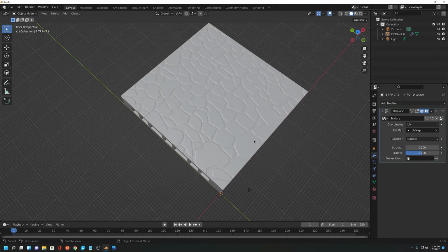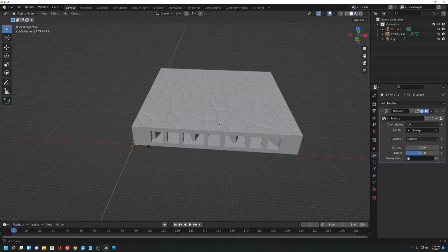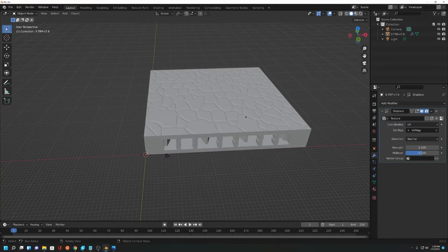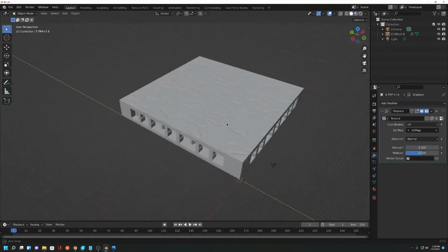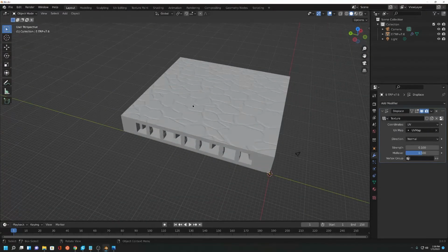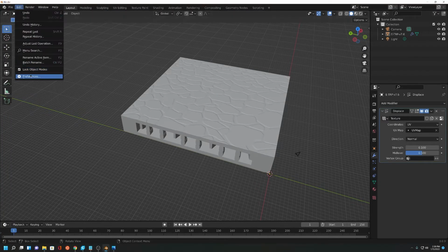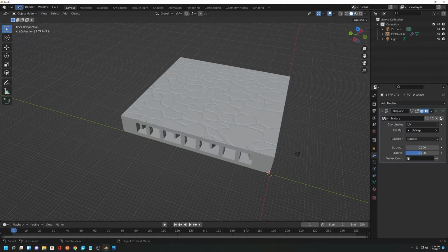So another thing that you want to do before actually exporting those, and we'll fix that here in just a second, re-export, is there's a feature add-on that you can have in Blender that makes it a whole lot easier to make sure that objects are manifold. I don't know if you've run into that problem, but what that means is basically your image isn't solid. There's corners wrong. Your printer's not going to be able to read it.